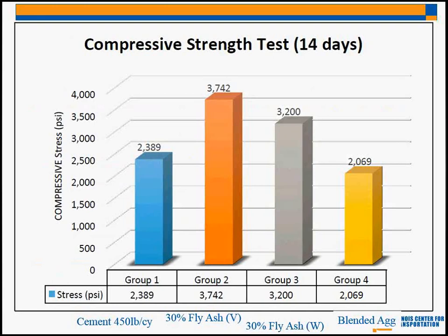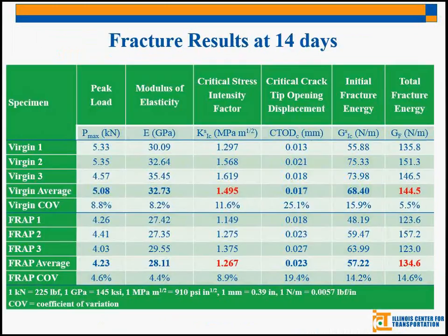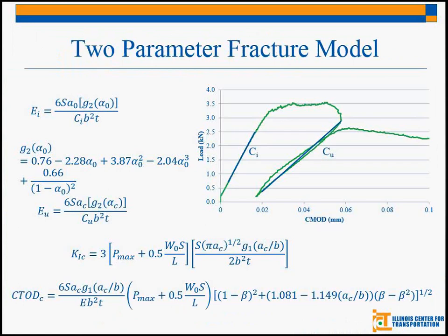Oh, yes. Sorry, I didn't mention that, but if you go back, again, when I rush through these things, I kind of forget. But yeah, every time we ran the fracture energy test, we load it to its top strength, and then we do an unloading curve when it reaches 80% of its peak strength, and then we reload it to get the unloading compliance. Many cycles, not like a few. No.